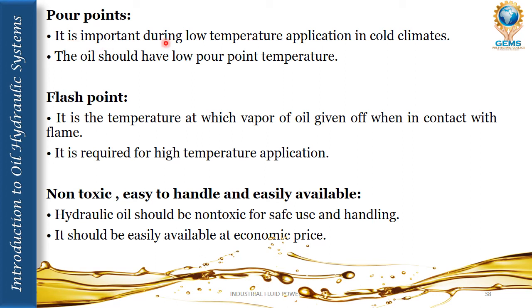Pour point. It is important during low temperature applications in cold climates. The oil should have a low pour point temperature. Flash point. It is the temperature at which vapor of oil is given off when in contact with flame. It is required for high temperature applications.